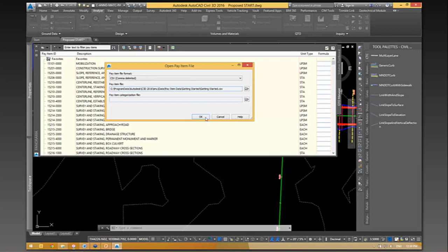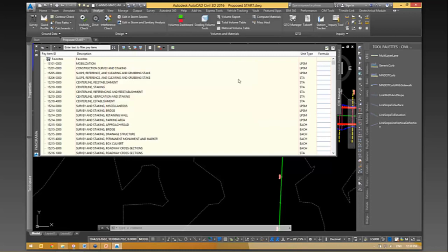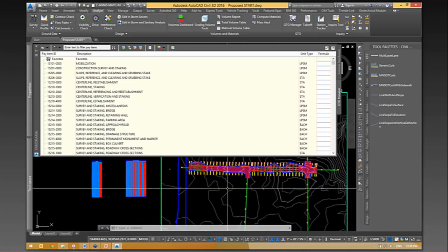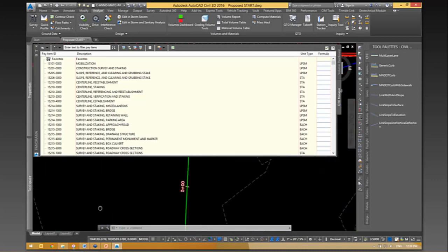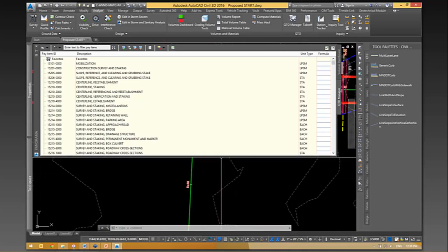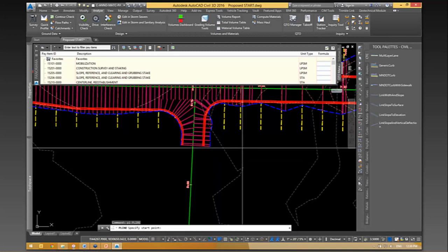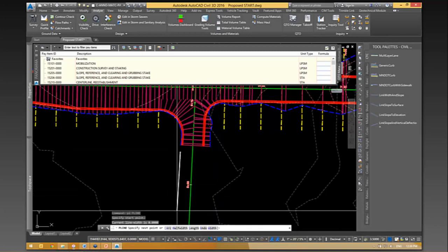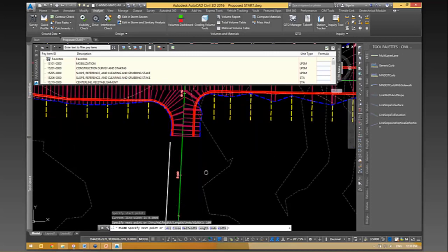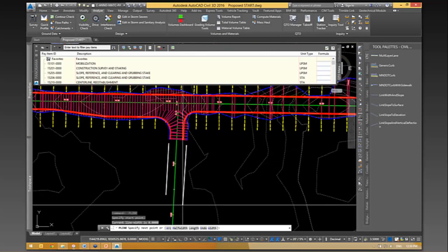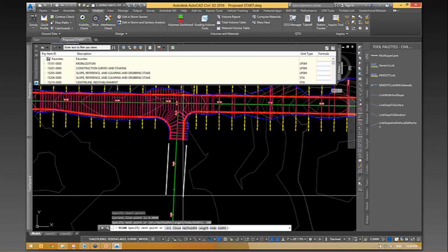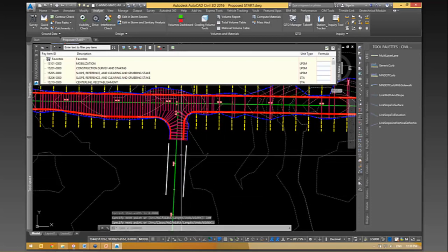So what I'm doing is pathing to that CSV. It comes in here. Here are those same three columns. And QTO Manager works fairly simply. Even without a corridor, I can use this thing. Say I had a couple of polylines here, and I'll draw these 100 feet long. There's one right there, another one right here, and these represent some curb removal, for example.